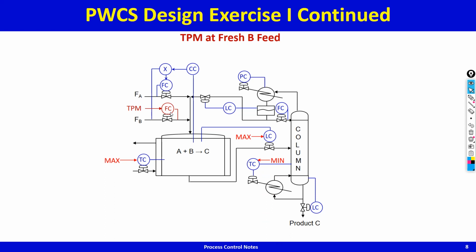The temperature controller should have the least possible set point, so that the purity of the product is at the quality guarantee that you're giving. So if the quality guarantee is 99 mole% pure product, then the purity of the product should be exactly 99 mole%, not 99.5, because then you're selling 0.5% product for free. So to minimize free product giveaway, the temperature controller, or the composition of the product, should be at the minimum guarantee for the customer. That is what determines the set point of the temperature controller,